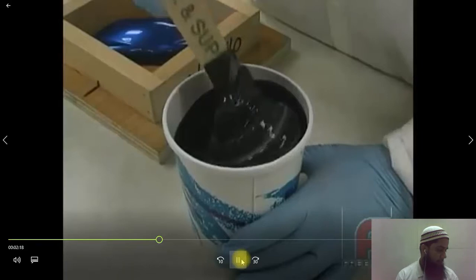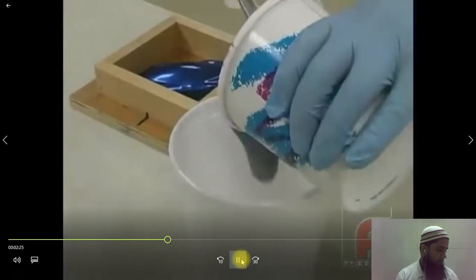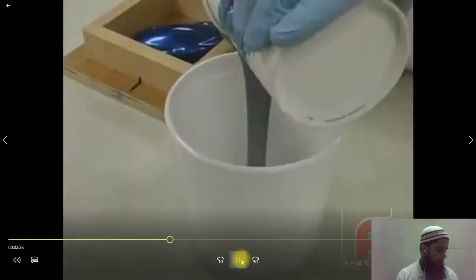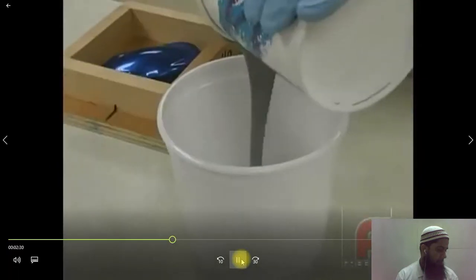Once the base and catalyst are fully mixed, we poured the mixture into a larger bucket for the degassing process. Since the mixture will rise while degassing, you need a larger container to hold the silicone rubber. Once it is properly weighed and mixed, our V340 is ready to be vacuum degassed.